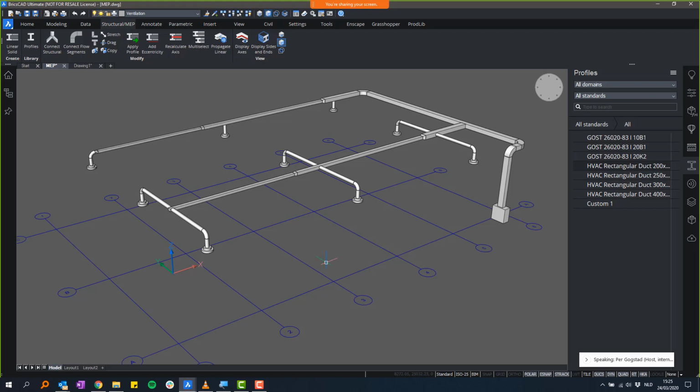Okay, so I think I understand what you mean. You can get this information through tools like data extraction, so you can extract information about the walls in one or more XREFs inside your main model. However, not in model space, because in model space, again, it's the same as in AutoCAD, you just select the entire thing as one block.